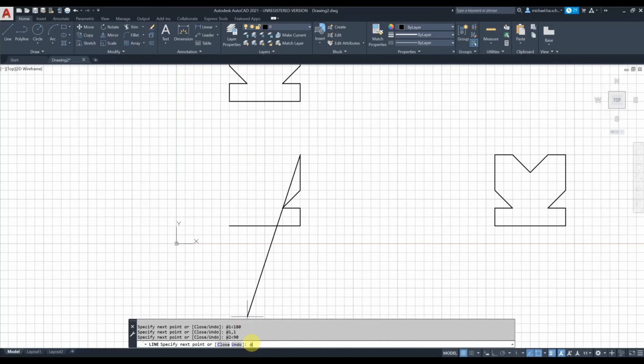Add sign, then length is 1, the angle is 180. Again, here we are not going to use polar, we're going to use Cartesian coordinate and also relative input. So that'll be -1, -1. Add sign again in Cartesian coordinate, -1, +1. So that's in Cartesian coordinate. Then we're gonna switch back to polar.